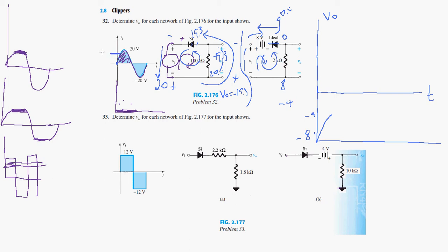And so when the voltage is equal to 8 volts on here, so a point here, more or less 8 volts here, the diode will become reverse biased in this direction, and so that will be an open circuit because we have 8 volts in this direction, minus 8 volts, so we'll have 0 volts at this point here on the diode. So this diode will be open, and then if this diode is an open circuit, then the voltage will become 0.